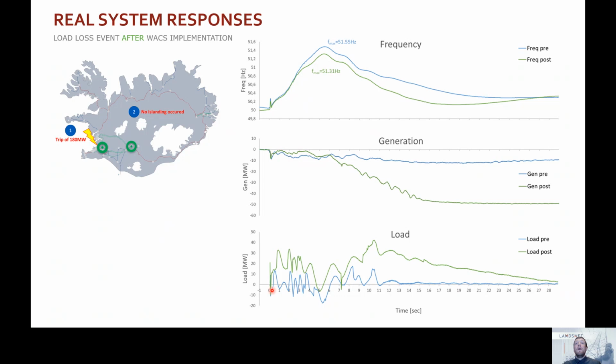Same here, the customer. In this case, we were asking this particular customer to increase its load by 30 megawatts. So of course it increases by roughly 30 megawatts, but it will still oscillate because of the excursions in the frequency, but we're still getting roughly a 30 megawatt offset. And then it will ramp automatically back down. And this really doesn't affect any of the production of the smelters themselves. They really don't notice. But this is really helpful for the grid.